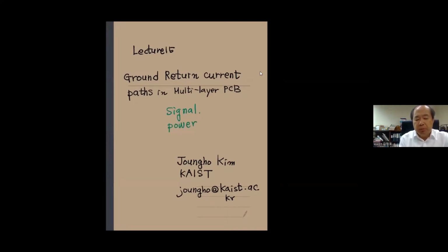So we wanted to minimize the impedance. Also, we have to control the resonances. And the PDN impedance has the inductive part and capacitive part and resistance part. We want to add some capacitance, but we want to minimize the inductance and resistance. And depending on frequency ranges, sometimes we are adding decoupling capacitors at the PCB level. Sometimes we are adding decoupling capacitors at the package level and on-chip level, depending on frequency range.